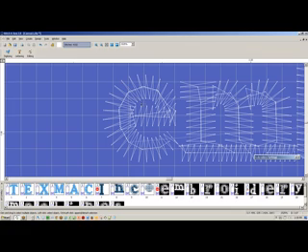That's your minimum stitch. And the reason we set that as a minimum is because at every one of these stitch points, the needle is going to make a hole about the size of these blocks. Because a 75/11 needle is 0.75 millimeters wide, sink that, move over at least 1 millimeter, and it'll sink into here, another hole the size of a block.